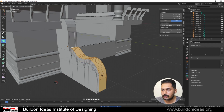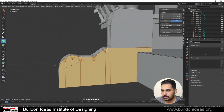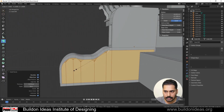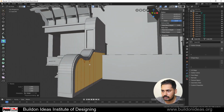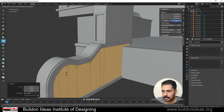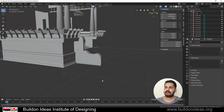I'll just have an extrude along the normals, and then I just give an insert for this as well. Slightly scale it in Y direction just to make sure that it is evenly proportional, and then I just give an insert extrude to that by clicking and dragging it inside, just like that. So this is basically the sopanam for me.